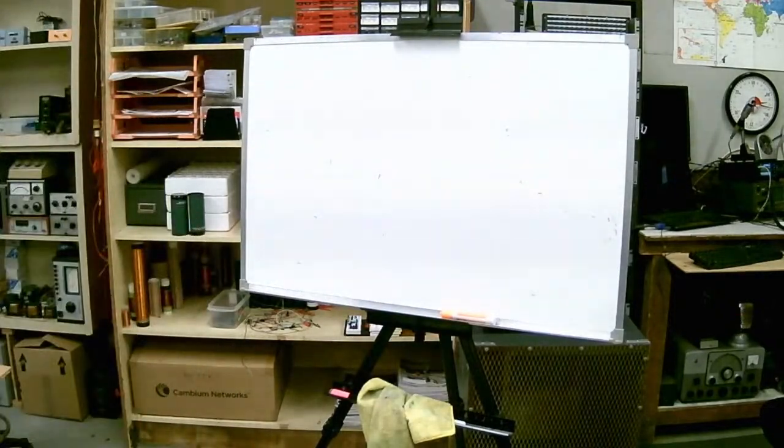Tell me about modulation. Well, that's the actual information. The carrier is actually the radio frequency. The radio frequency is 970, 970 AM. And the information you put on it changes the amplitude. So we vary the amplitude in accordance with the audio. I see. So it's changing all the time. So the first way of putting voice information on radio is amplitude modulation. Now, it's not the only way to do it, but that's the oldest. So that's what AM stands for, amplitude modulation. So we do that.